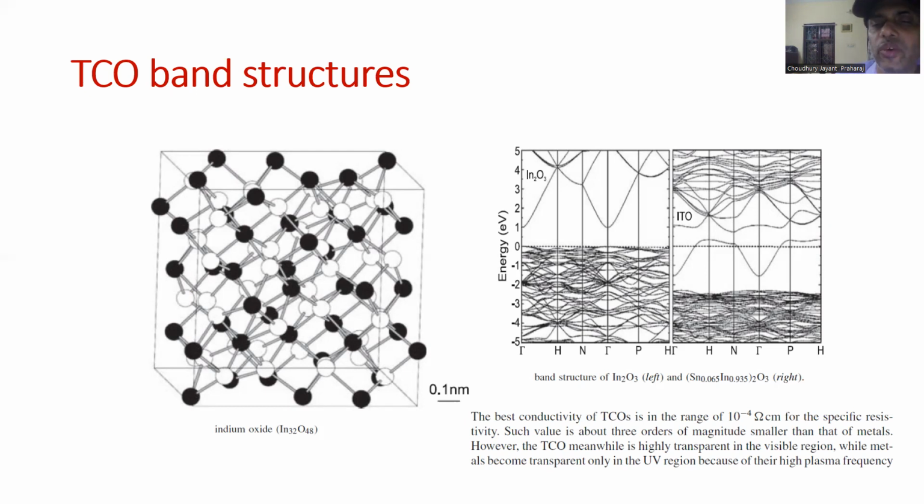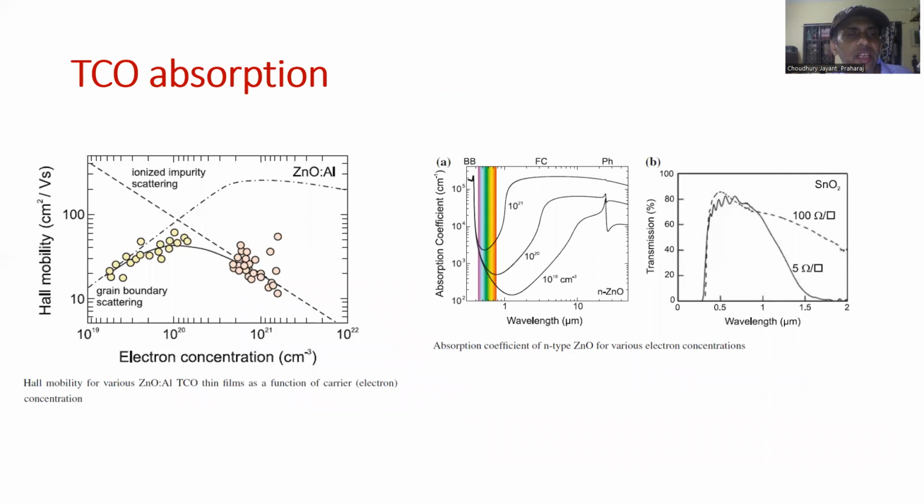And we typically want low reflectance, and these transparent conducting oxides from these material systems can be used to obtain low reflectance transparent conducting oxides for use as front contacts in these solar cells. This slide shows some typical absorption coefficients and transmission coefficients in these transparent conducting electrodes made from these materials.